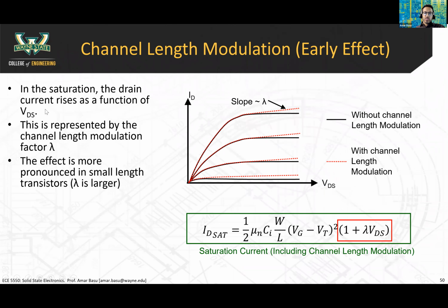Okay, so the result of this, and I'll go into a little bit more detail in the next slide, is that instead of looking like the black lines that you see, the black lines represent the ideal transistor characteristic. And the ideal characteristic, once we got to saturation, was a flat horizontal line. Now that was great, because when you want to build a current source in circuits, a current source has a flat horizontal line like this. So the MOSFETs could be used as an awesome current source. And in fact, they are.